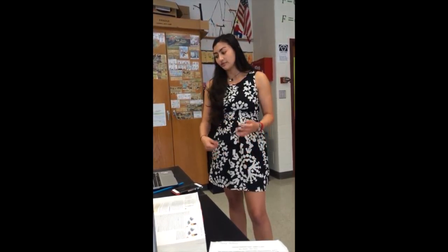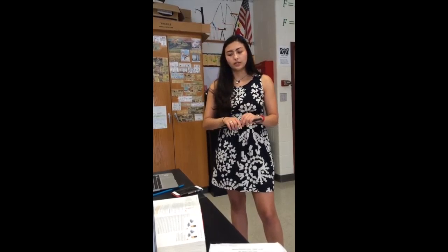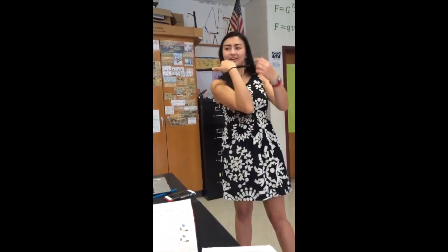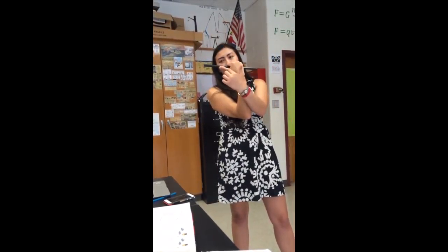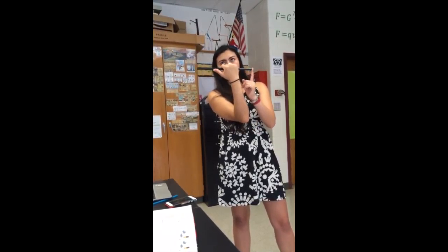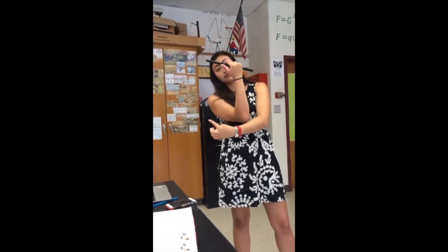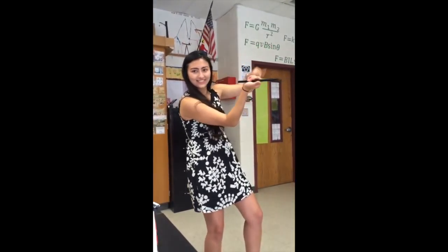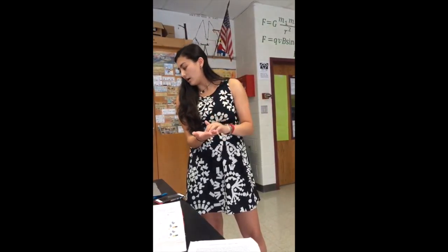The second method you can use is to determine the direction of a magnetic field produced by an electromagnet relative to the flow of the conventional current. So imagine holding an insulated coil perpendicular to your body. Okay, your thumb represents the flow of the conventional current. Positive goes into the south end of the coil, and negative comes out of the north end. So your fingers are the direction, once again, of the magnetic field. They go around.